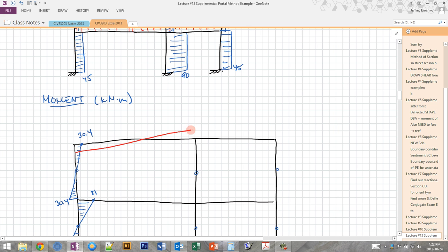And this comes like this. This actually has to cross at the hinge at the center. And this is equal to 30.6. Now this is not exactly equal, but that's due to our round-off error, so it's close enough. And we have compatibility of this moment around the corner. So the compression side is always on the inside, which, if you'll remember from our displaced shapes and from all of our other analyses of determinate structures, has to be the case all the time.